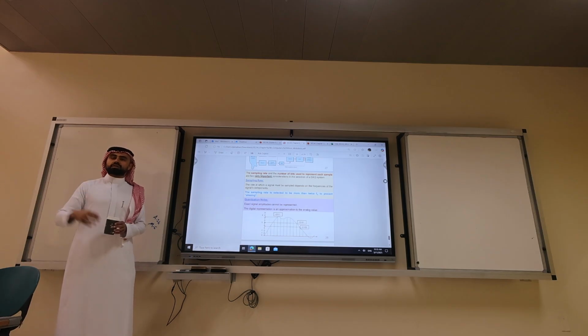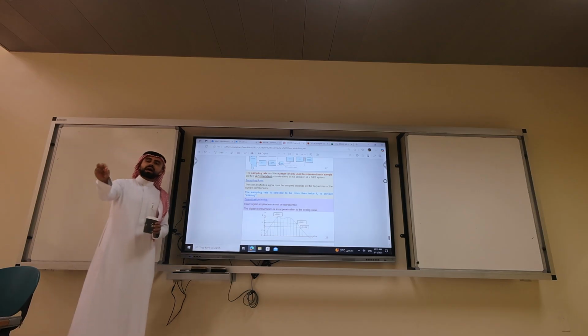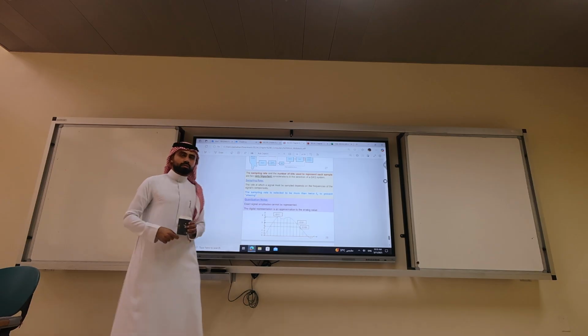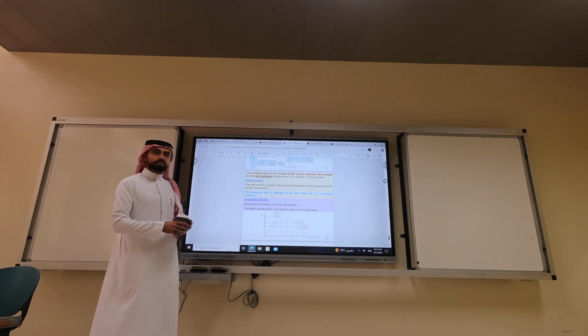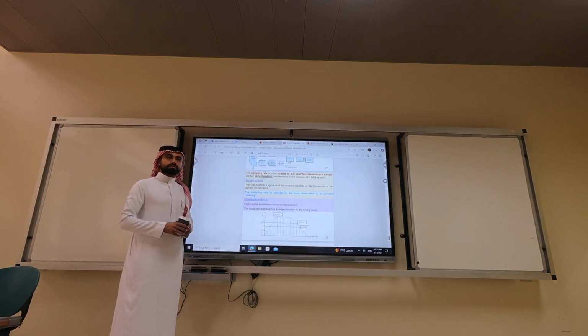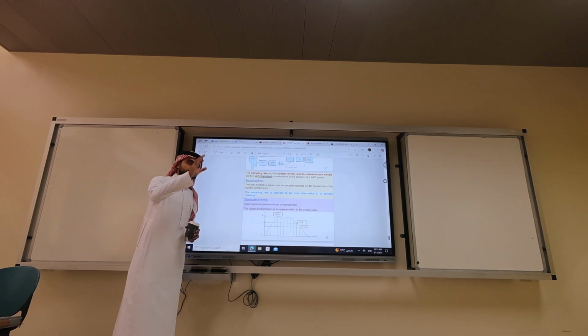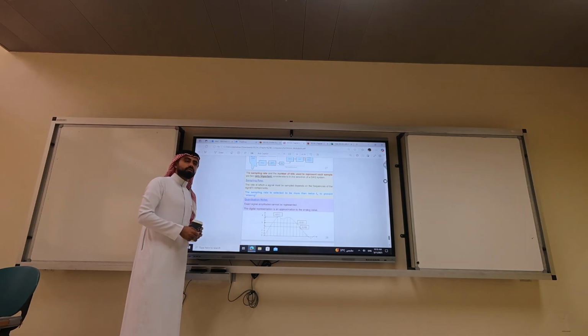They call it the Nyquist theorem. You will study the Nyquist theorem in the control course. Who will be taking the control course in the summer? You will see this. If the frequency of the signal you're studying is 10 Hertz, what's the minimum sampling frequency? Twice. 20. Double.